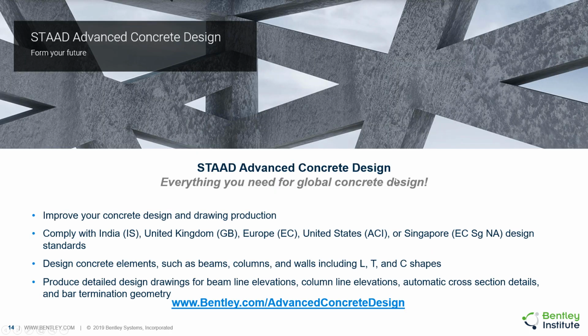STAAD Advanced Concrete Design, otherwise called RCDC, is also included in STAAD.Pro Advanced, which is in turn included in the Structural Enterprise license. And you have seen the features of this program today. It's available for various international codes, and the Eurocode, Singapore National Annex as well as Malaysian National Annex is also available. ACI metric is already available. ACI Imperial is coming up very soon. This designs not just the standard beams and columns, but also irregular cross sections such as L shape, T shape, etc.